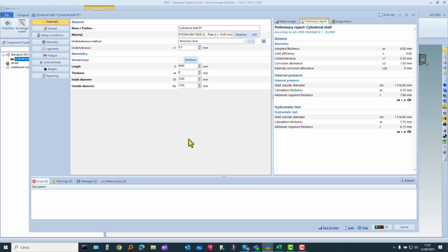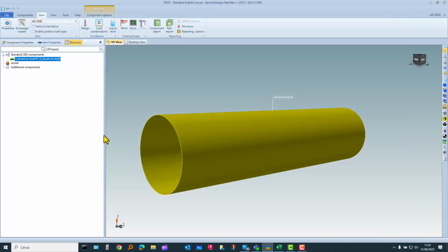With a lower temperature, maybe we could have an advantage on the design stress and on the thickness, because in the German pressure vessel standard we have seen that there is no correction for the tensile strength at relatively low temperatures. The nominal design stress is always, as in the Italian code and as in the harmonized standard, the yield point divided by 1.5. We close this.